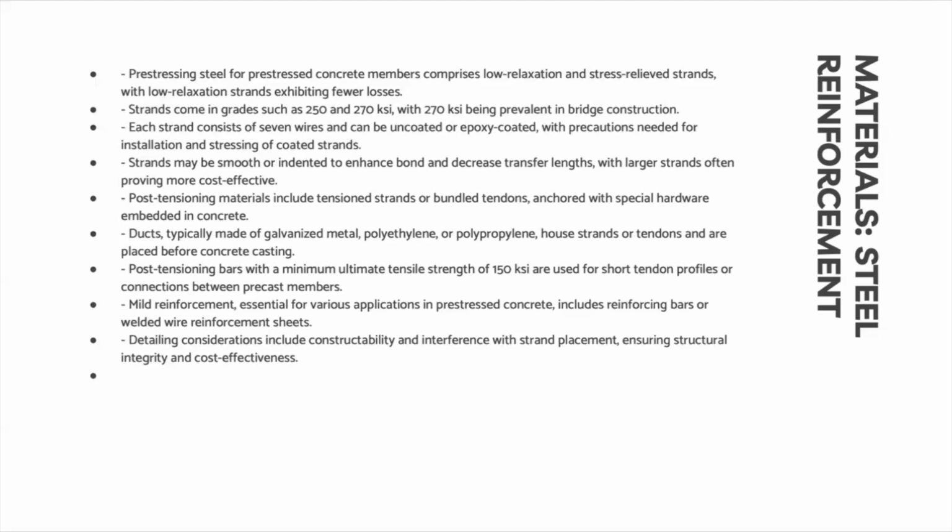Furthermore, detailing considerations include strand placing, spacing, and diameter selection, with fewer larger strands often proving more cost effective despite being stiffer and more challenging to work with.